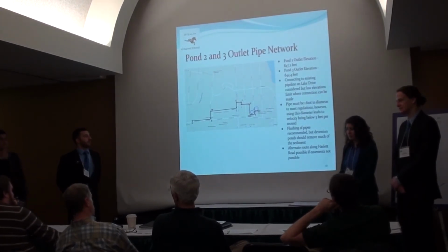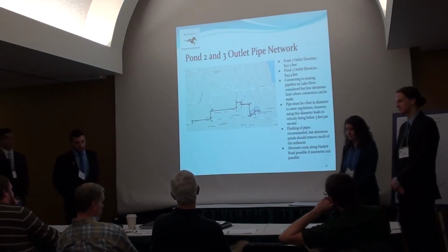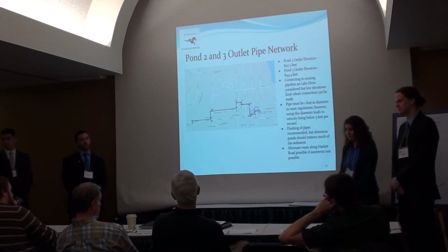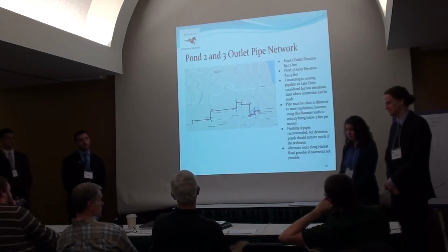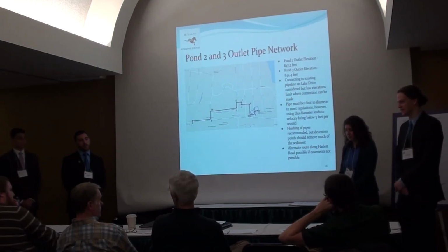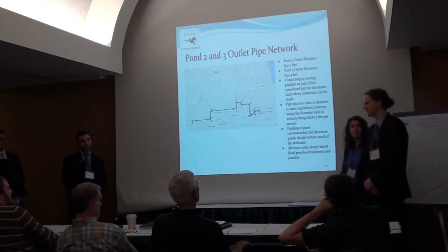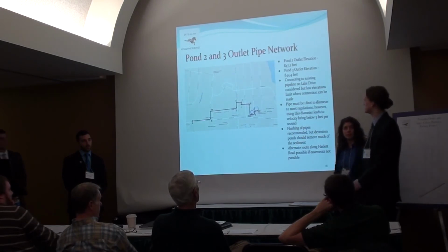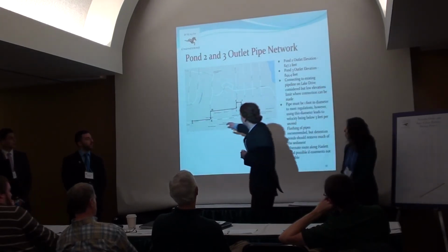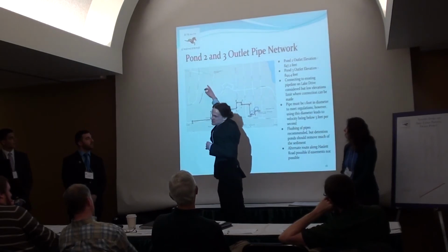Have you considered, as you're looking at this layout and thinking in terms of water surface profiles, for example, did you look at flood elevations in the Pine Lake outlet drain? Yes. And what are the flood elevations relative to what you're looking at through water surface? The flood elevation is at 848 feet, so it reaches out to here and extends up this way.